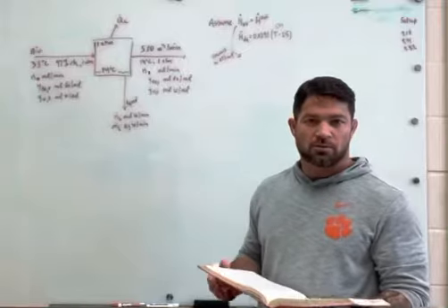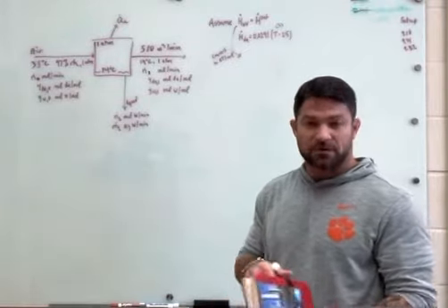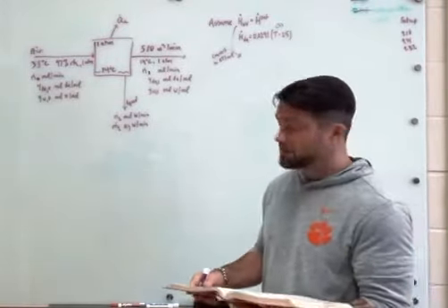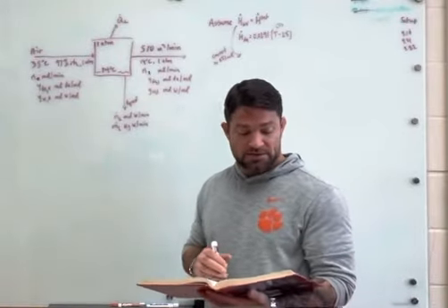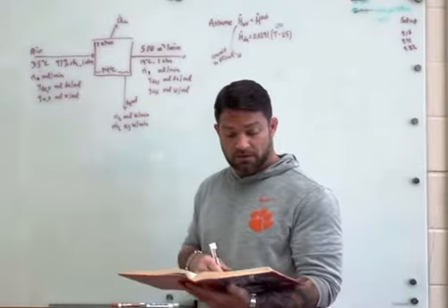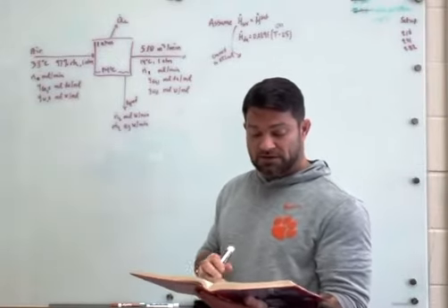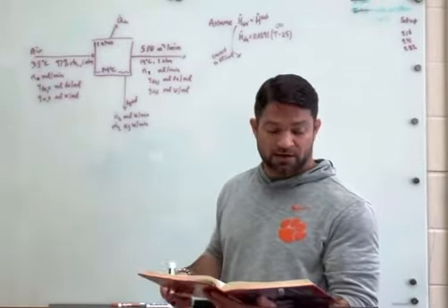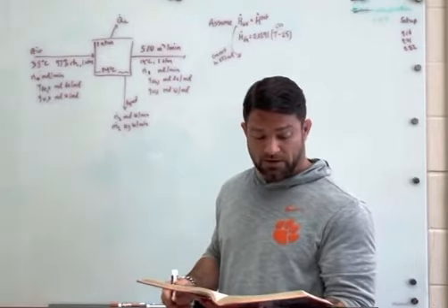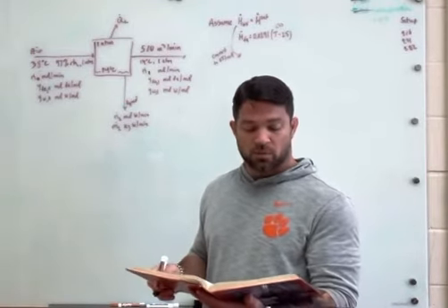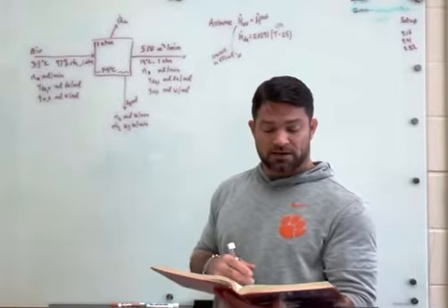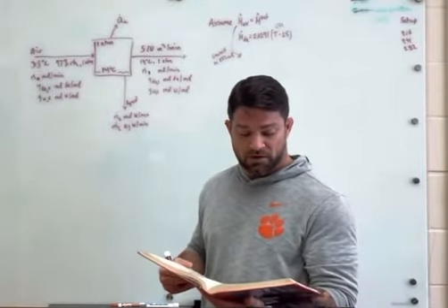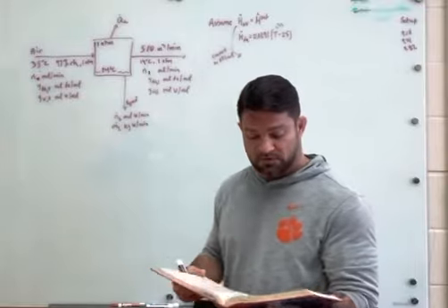We're going to work through problem 7.45 of Elementary Principles of Chemical Processes. In this process, air at 38 degrees C and 97% relative humidity is cooled to 14 degrees C and then fed to a plant at a rate of 510 meters cubed per minute. We're asked to calculate the rate at which water condenses and the cooling rate in tons, where 1 ton of cooling is defined as 12,000 BTU per hour.